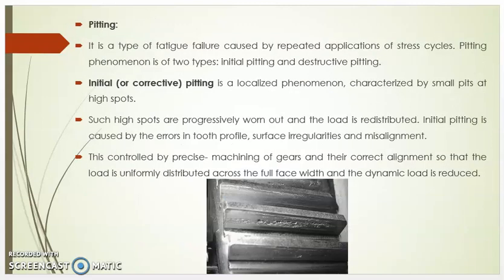Pitting. It is a type of fatigue failure caused by repeated applications of stress cycles. Pitting phenomenon is of two types: initial pitting and destructive pitting. Now we will see first of all initial or corrective pitting. It is a localized phenomenon characterized by small pits at high spots. Now you just see this figure.